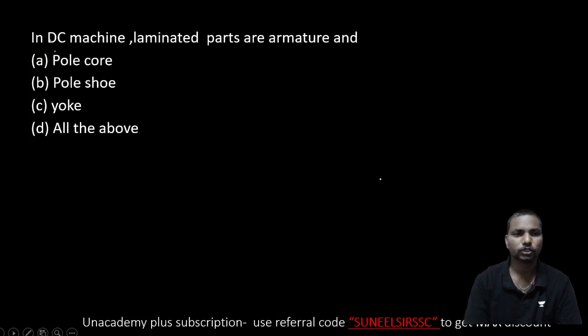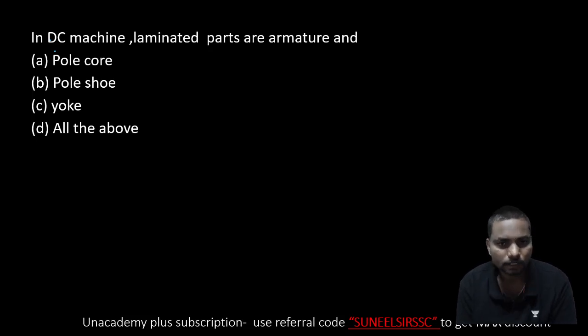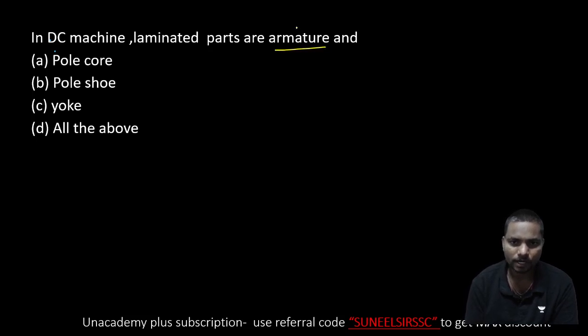Okay, coming to the next question. DC machine laminated parts are armature and also dash. What are the parts that are laminated in a DC machine? Here the armature is laminated, we have already discussed this one. Now coming to pole core, pole shoe, yoke and all of the above. So what is the yoke? The outer frame is nothing but the yoke.